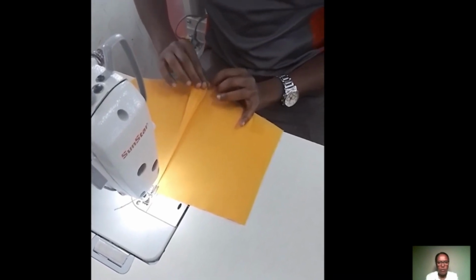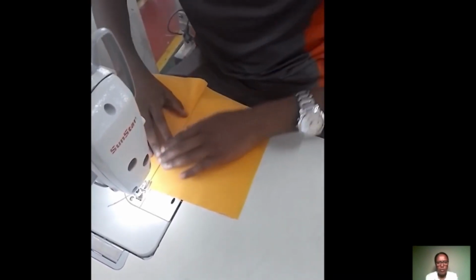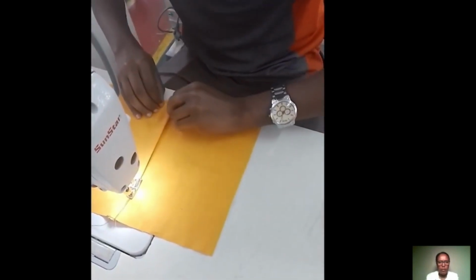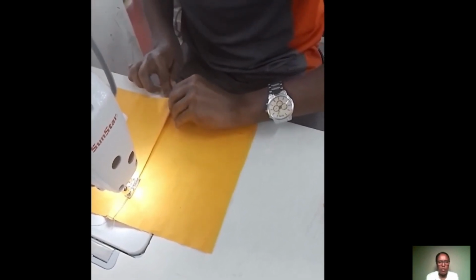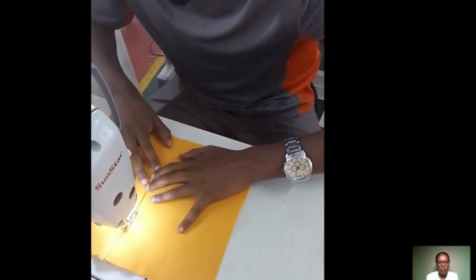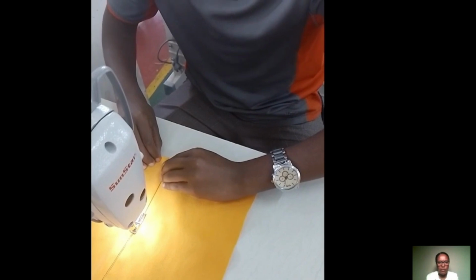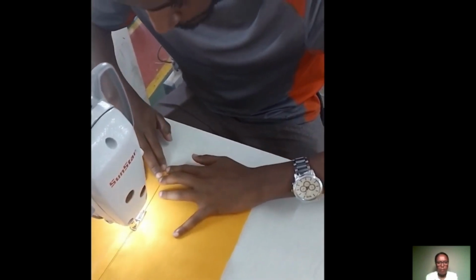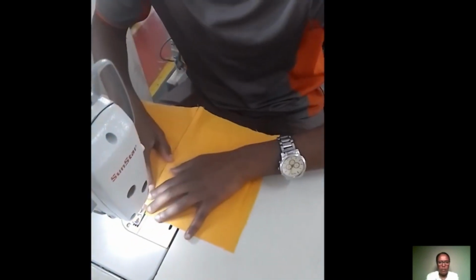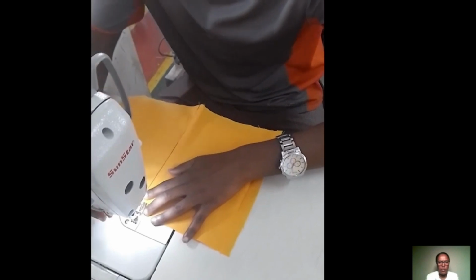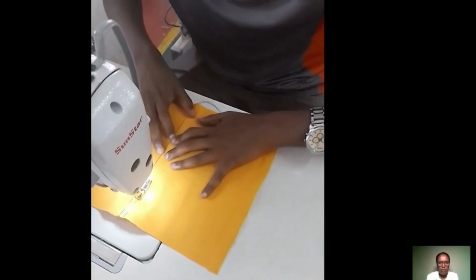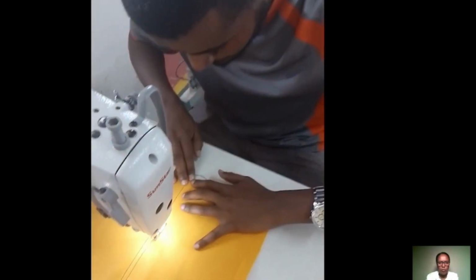During the sewing, the operator should check the back part of the fabric to see whether it is folded correctly or not. So after finishing the first sewing, it needs another stitch line, because this lapped seam has 2 stitches.